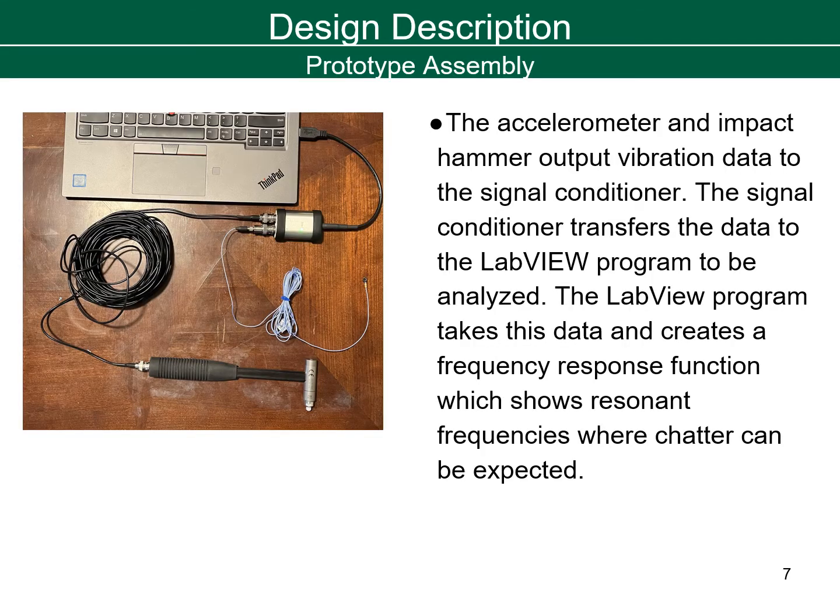The accelerometer and impact hammer output vibration data to the signal conditioner. The signal conditioner then transfers the data to the LabVIEW program. The LabVIEW program creates a frequency response function from the data.